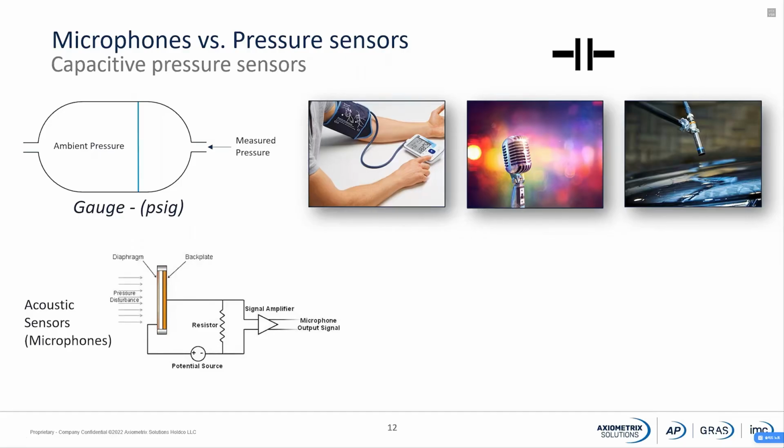So how is an acoustic sensor or a microphone working? Well, in front of the microphone you have a diaphragm, and then you have a backplate, and the pressure is changing the distance between the backplate and the diaphragm. Therefore it is called a capacitor or a capacitive microphone. If the distance between the two plates is changing, then you can get a signal that is equally big as the pressure on top here.